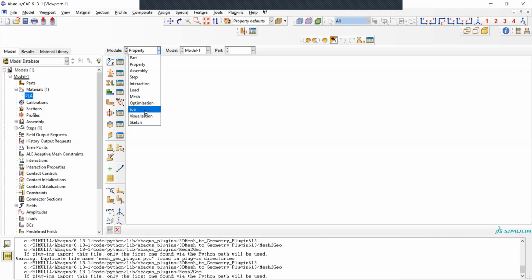When the simulation is done, you have results. This is where you load in visualization, and this is where you can analyze the results. And you can extract plotted lines, you can extract section views, you can extract von Mises stresses, you can extract displacement along special vectors. So you can decide how to analyze the result.